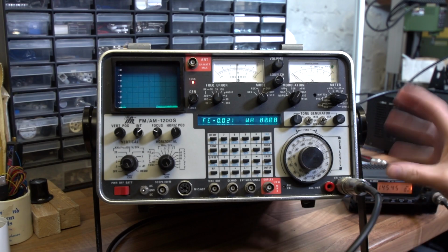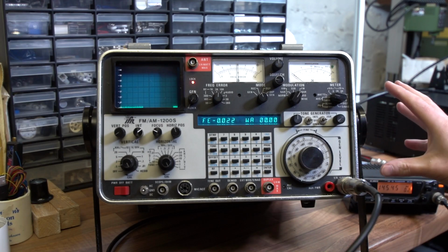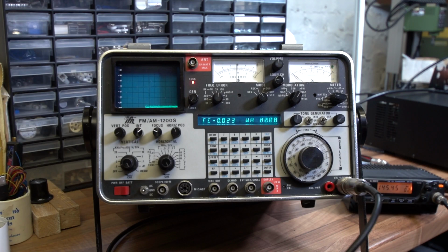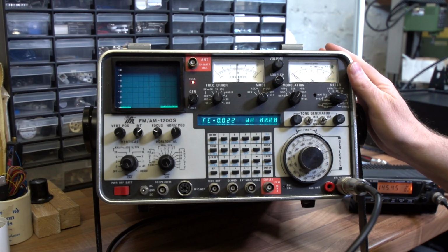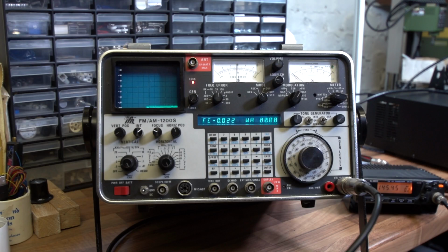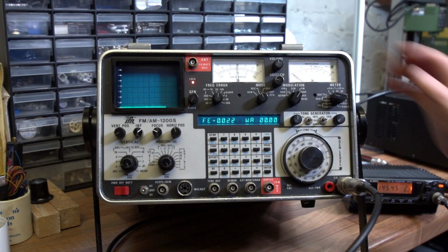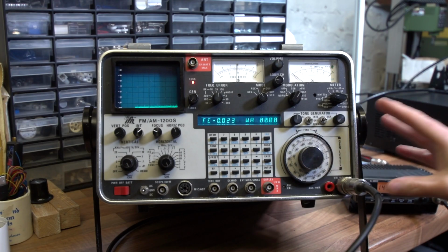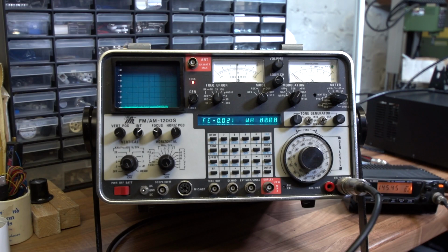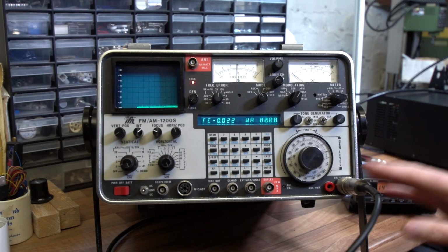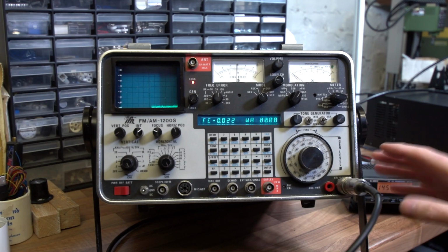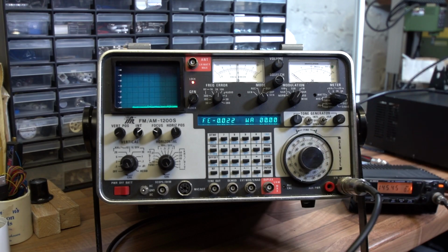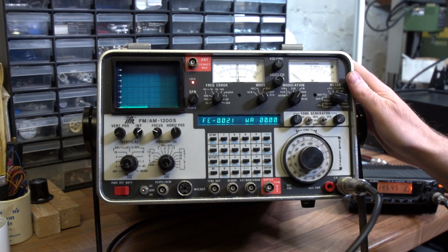There's actually a big dummy load in there, a 50 ohm load, which in this particular model will take up to 150 watts for a short period of time. Probably for about a minute maximum before it gets too hot. But it will comfortably take 50 to 100 watts. And as I say, that's something you cannot do with a standard spectrum analyzer. You would fry the thing if you tried to put RF energy straight into it at that kind of level. You'd destroy it. So it is designed to take power, and that's the beauty of these test sets.